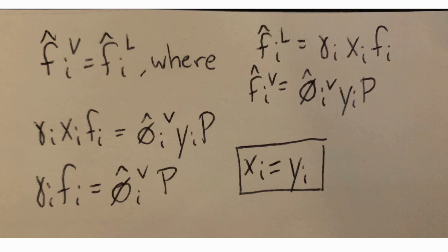To do so, it's best to start with the equations for fugacity in the liquid and vapor phases. Assuming that the system is in liquid and vapor equilibrium, the fugacity in the liquid is equal to that of the gas phase, and from here, the equation can be simplified by setting xi equal to yi. Additional simplifications can be made based on particular conditions, such as whether the gas can be assumed to be ideal.